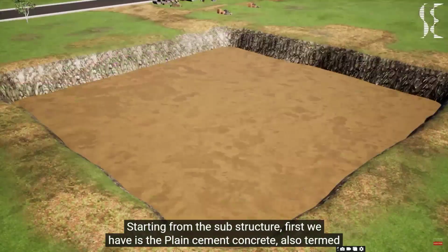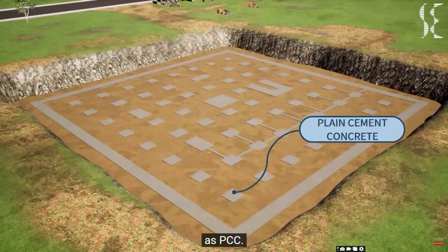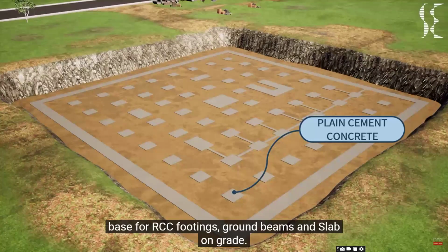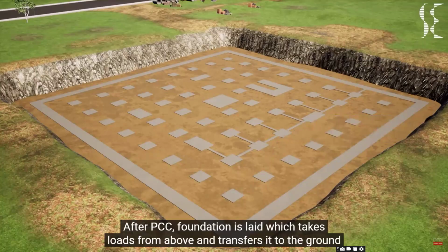Starting from the substructure, first we have plain cement concrete, also termed as PCC. It is a low-strength mixture of cement, fine aggregates, usually sand, and coarse aggregates. The main purpose of PCC is to provide firm, rigid, non-porous, impervious, and leveled base for RC footings, ground beams, and slab on grade. After PCC, foundation is laid which takes load from the above and transfers it to the